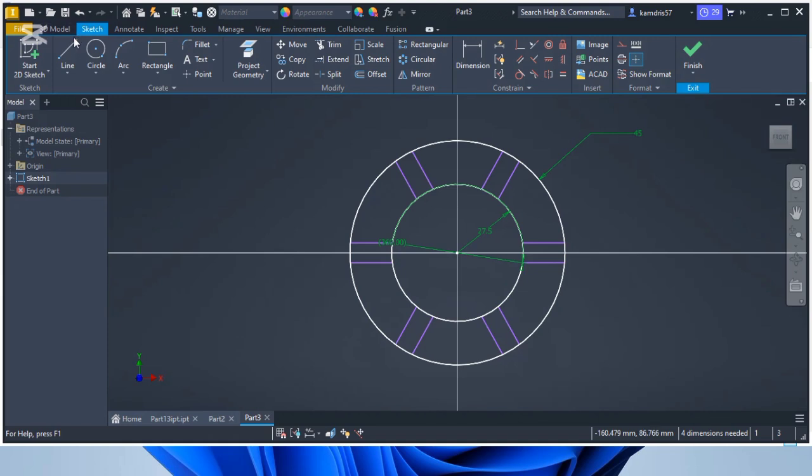So first make our line, which is a center line. So draw it here, which is 60 mm. Click on your tab to go to the degree. So it's at 56 degree. So we'll make it to be at 60 degree. Then click enter. So this is it. So now click on it to make it a center line. Okay. Now let's zoom in.